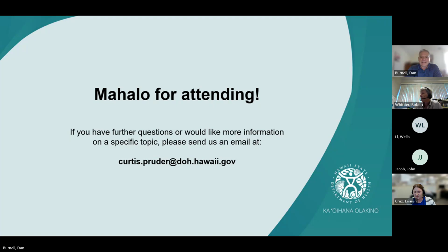Thanks, Bob. The next question, I'm going to take. Other than soil vapor extraction, are we employing any other methods of groundwater remediation? Why or why not? So I am aware that we have used air sparging and soil vapor extraction as a combination together at one site. There's also been sites where ISCO was used, so the in situ chemical oxidation.